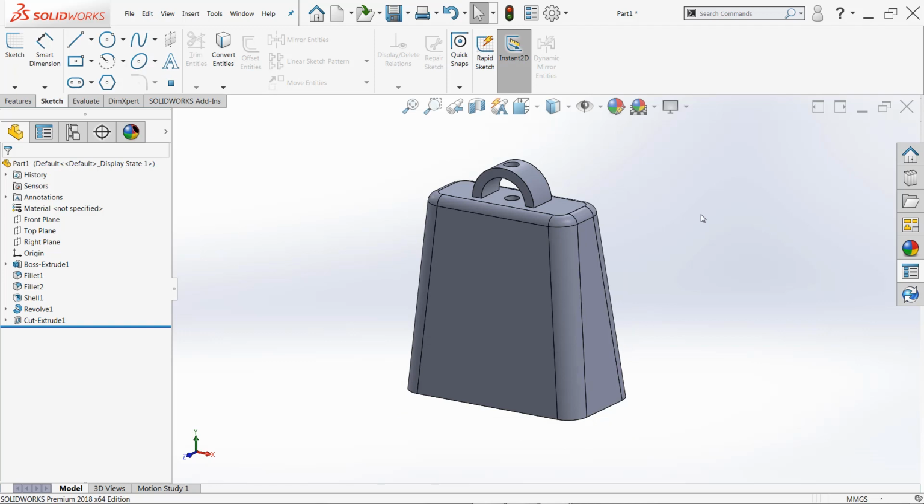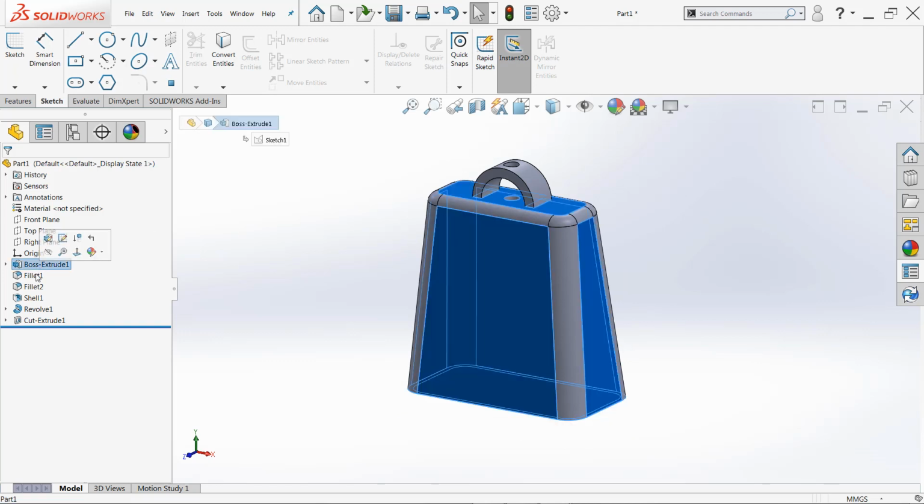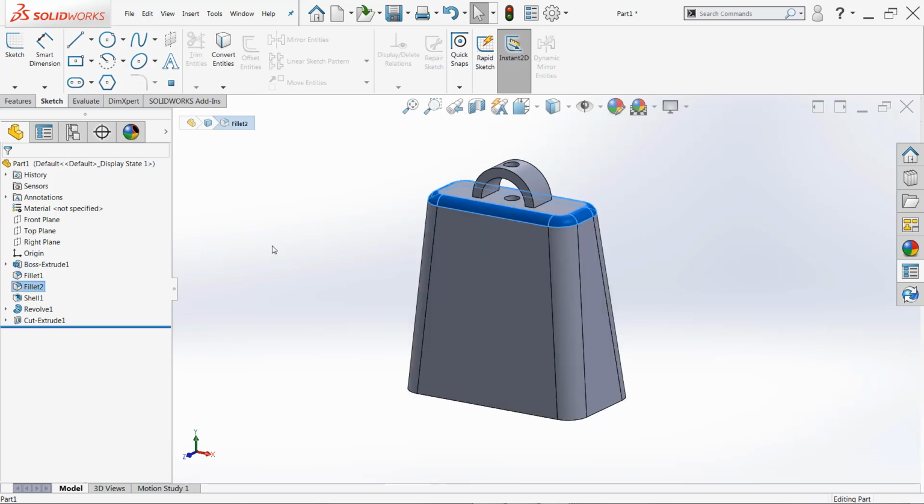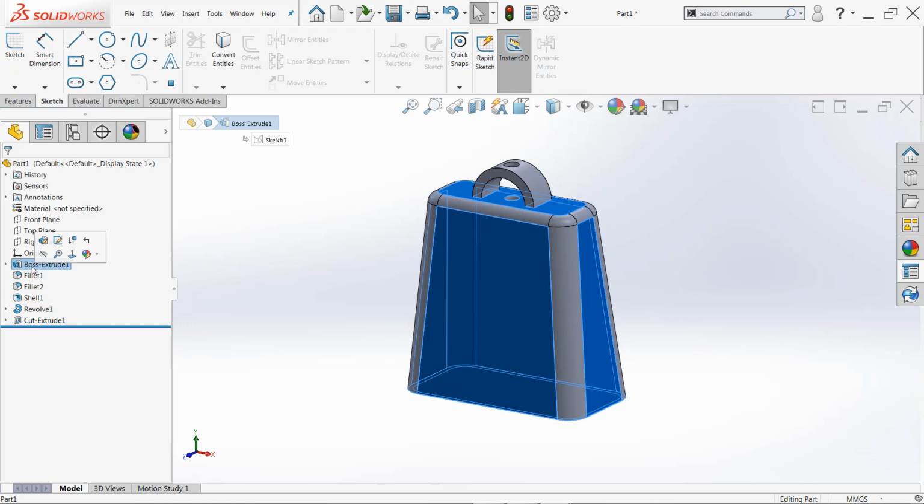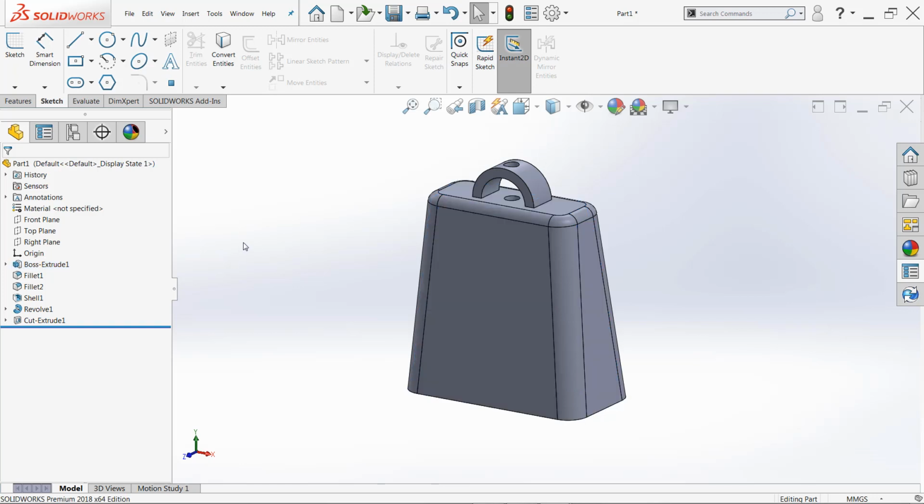Additionally, thinking ahead when you're editing features is going to be very important, especially when you're editing features near the top of the design tree, because there are downstream implications. And if you make extreme edits to features that are very high in the tree, you may end up breaking features down the line. So pay attention to that. Try to focus on understanding what the impacts will be if you make changes to features, and that should keep you in good shape.